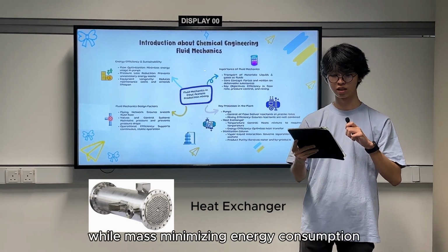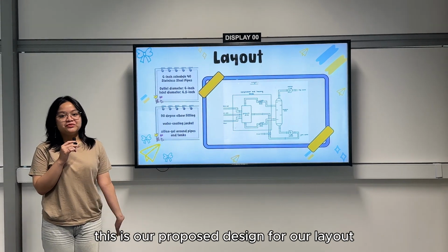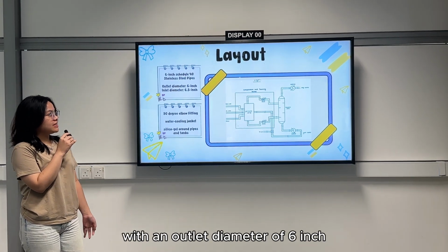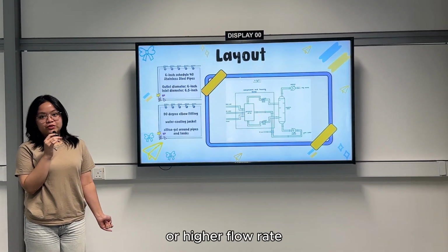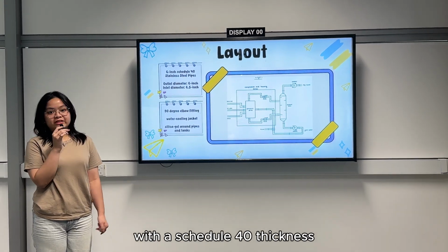while minimizing energy consumption. This is our proposed design for the layout of the plant, and we have decided to use 6-inch Schedule 40 stainless steel pipes with an outlet diameter of 6 inch and inlet diameter of 6.5 inch. To make sure that our plant can support a higher flow rate, we have decided to use 6-inch diameter pipes with a Schedule 40 thickness.